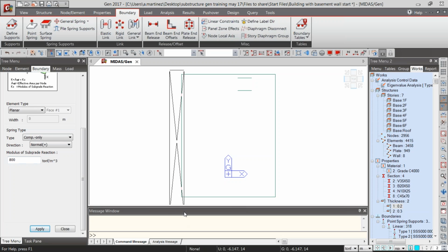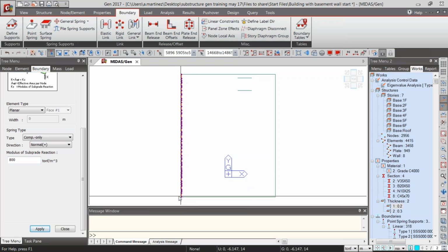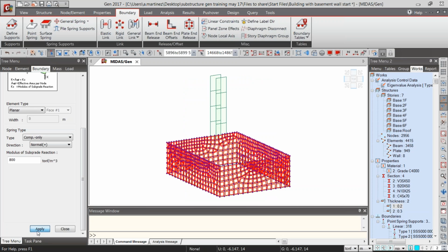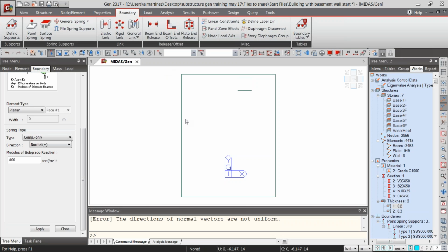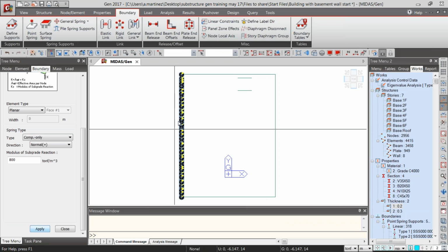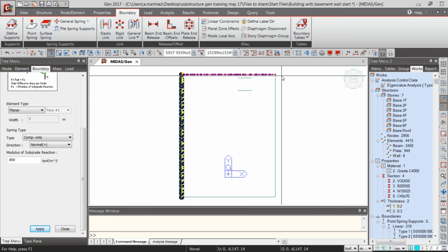And so we actually just go about and draw rectangles to select all of our wall elements. Actually, what we need to do is do these one by one, since they have different directions. I think you can just do each axis in parallel, but let's just do one by one, just to keep it easy, in sequence.